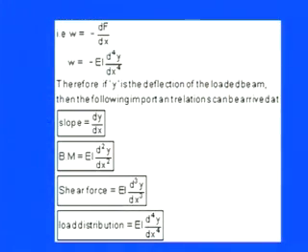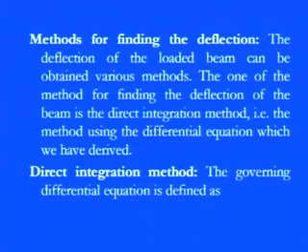One has to be very careful to check how one can easily get the bending moment, shear force, rate of loading or slope with the single, second, third or fourth derivative. With those components, we now want to find the deflection. There are various methods available, and one of them for finding the deflection of the beam is the direct integration method.